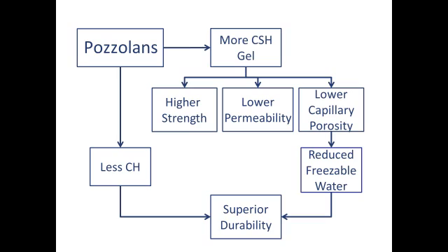Well, those pores are plugged, so our concrete has less permeability, and there are fewer open pores to hold water, and that open water, there's less of it, so we have better freeze-thaw resistance. So there's less free water in the concrete to freeze. Water can't get in. There's not that many spaces for it to be in, so we have superior durability concrete. And that's the general sense of this, why, in a single slide, I always use pozzolans in all of my concrete.